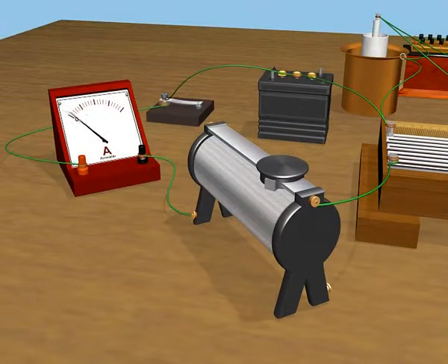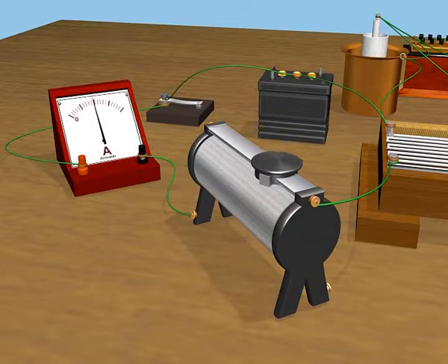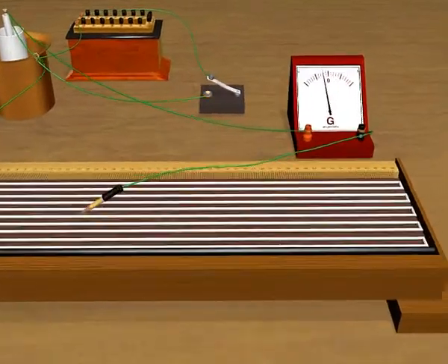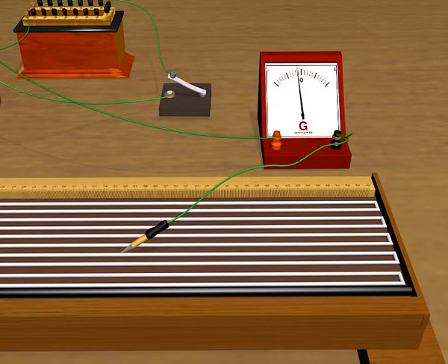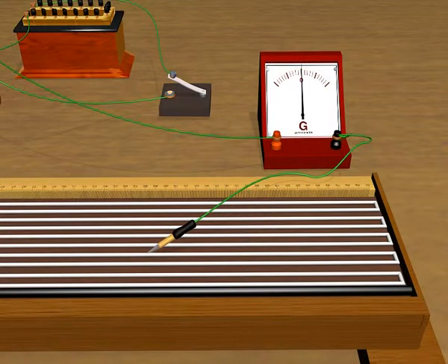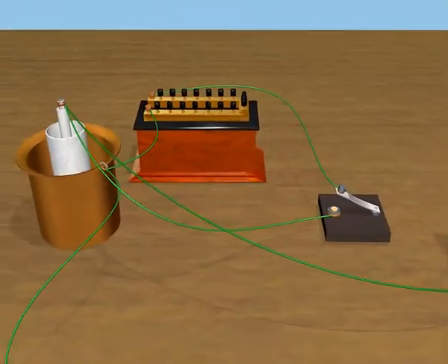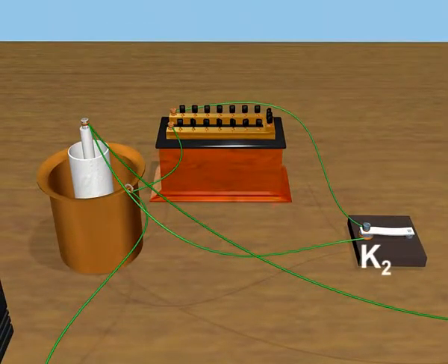Without inserting the plug in the key K2, the rheostat is adjusted and kept fixed for constant EMF. The jockey is gently slid over the potentiometer wire till a point of no deflection is obtained on the galvanometer. The null point position is obtained accurately and the balancing length L1 for the EMF of the primary cell is noted. The shunt resistance is connected by inserting the plug into the other one-way key K2.